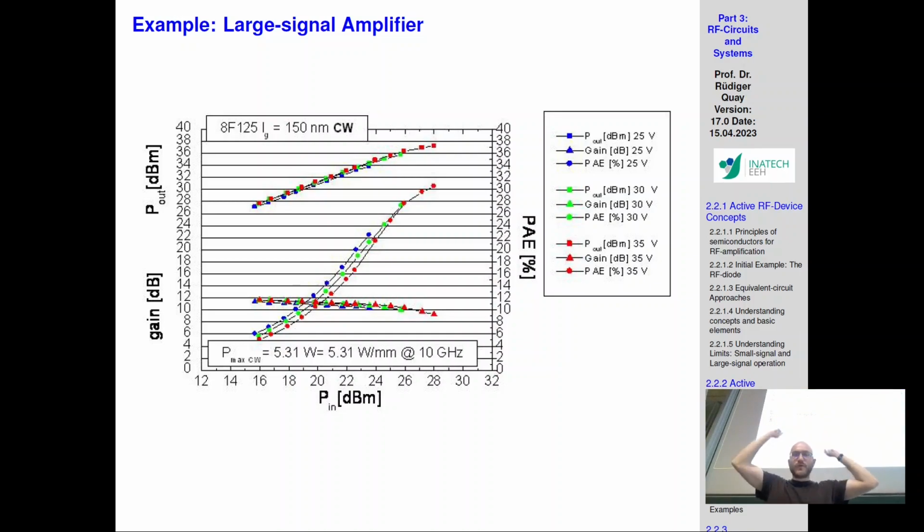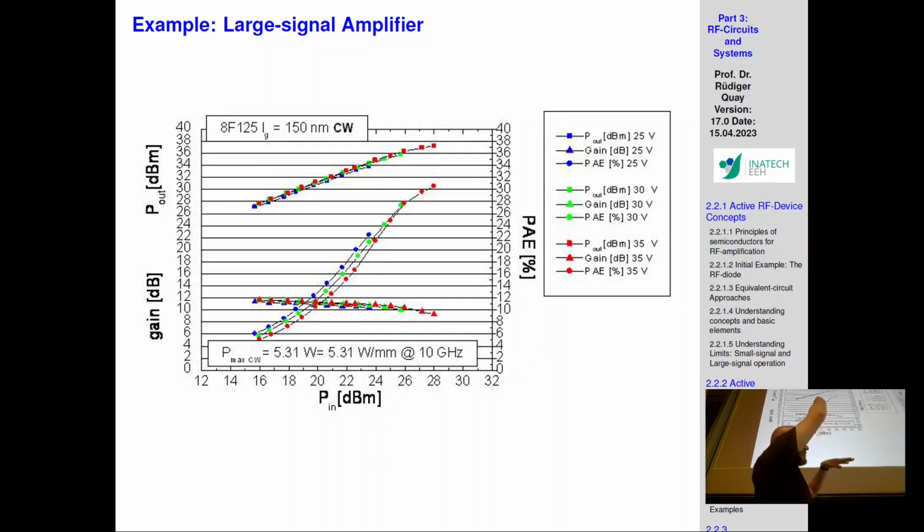So what is the power efficiency? And we saw that the Doherty had this weird curve, which was big here, and then had a little slump, and then it got bigger again, and then it went back. And the curve was underneath the depicted input power and then the efficiency. Here we can see a similar curve. We have input power on the horizontal axis and two vertical axes. One is depicting the gain and the output power, and the other one is depicting the efficiency, the PAE. PAE, what is PAE? It's the power added efficiency.